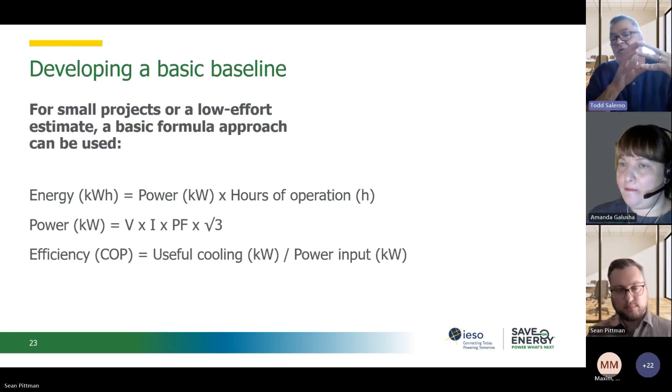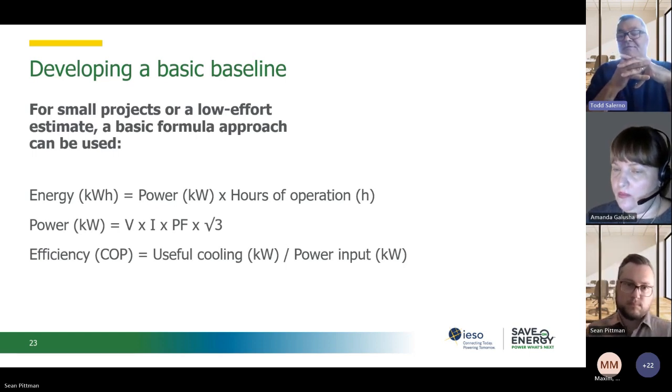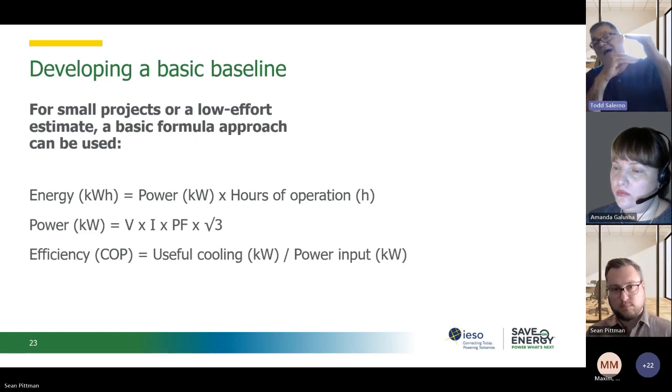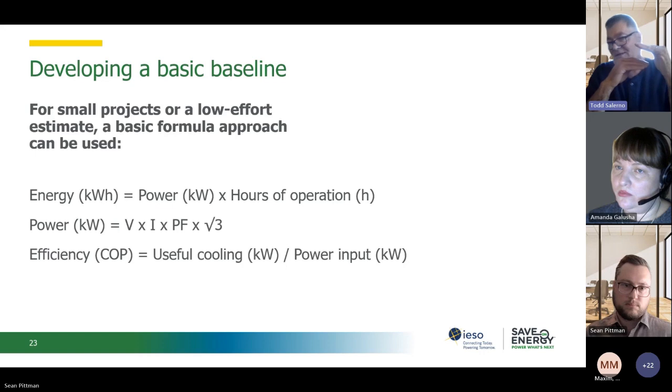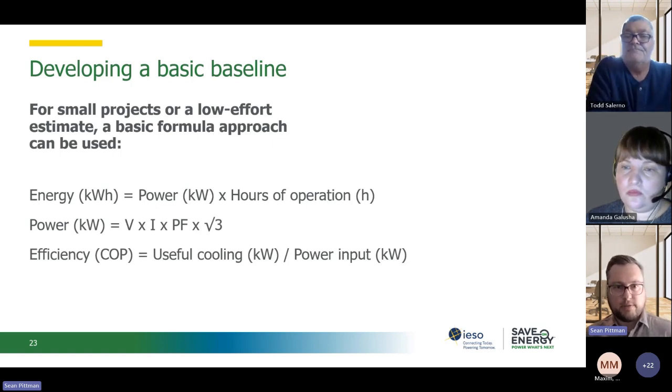But the one advantage to doing it that way is you are doing a fairly conservative estimate. So you know that the existing system will not be at an efficiency higher than what those published values are, most likely. It'll be somewhat less. So you're conservative in your savings estimates. That way you don't make an error on the high side. Correct. Yeah. Wherever we're making assumptions, always best to err on the side of conservativeness. It's usually a safe bet.